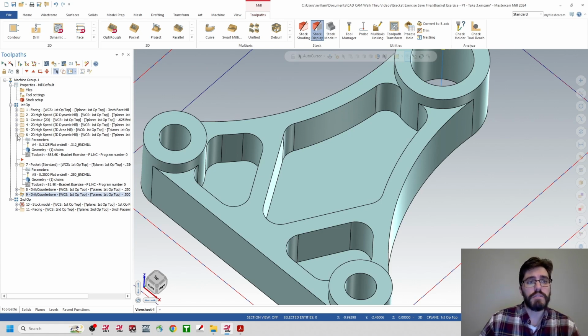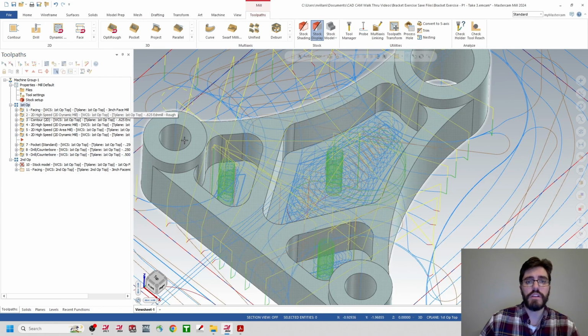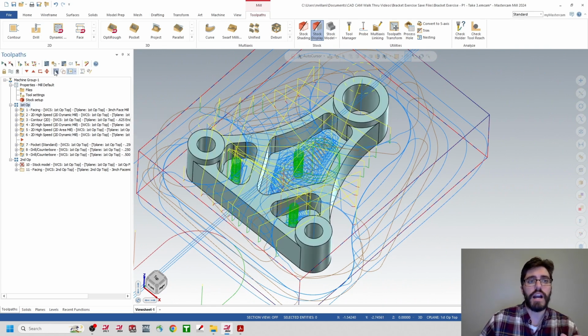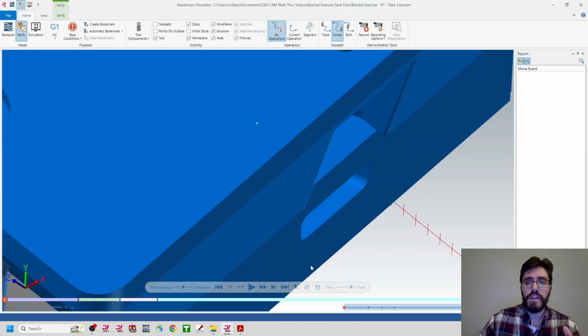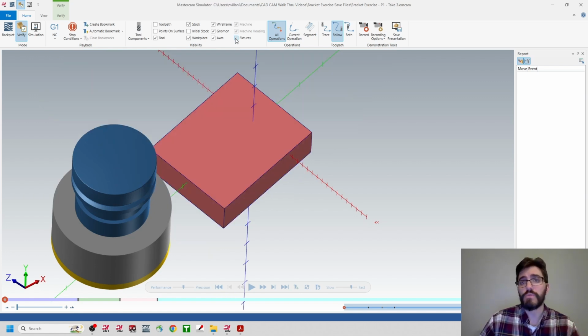So I'm just going to go ahead and minimize the 6th and the 7th toolpath, and then I'll click on the entire first operation here, and zoom out a little bit. With this entire first operation selected, I will go ahead and select verify selected operations to see if this matches up to my new P2 model. So I'll click on verify selected operations, and then I will let this run. And this again is a very important reason why we probably want to have our fixtures separated into separate levels, because right now my fixture is obscuring my entire first operation, and I can just toggle my fixture off and I don't have to worry about it.